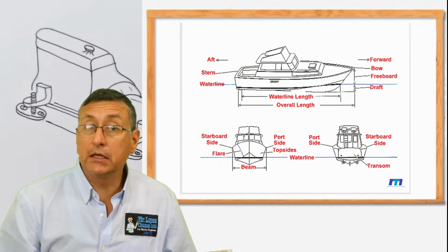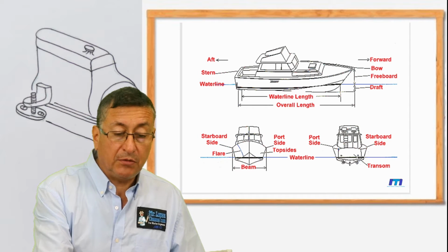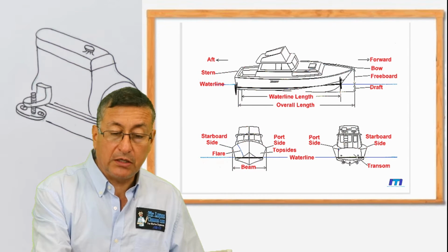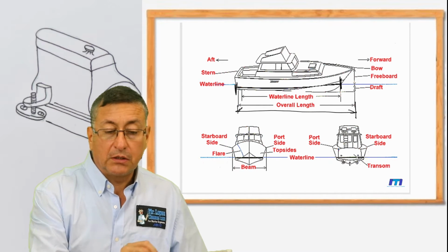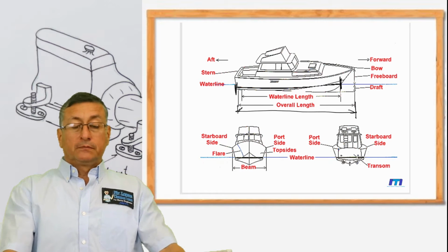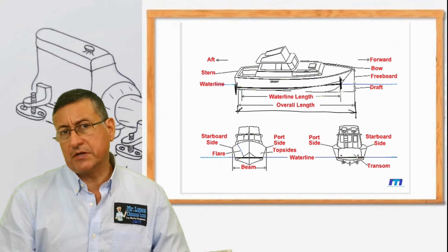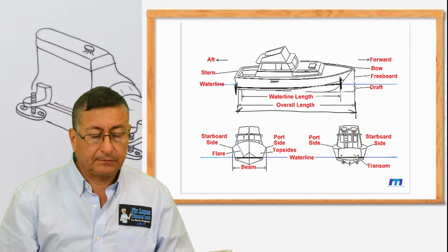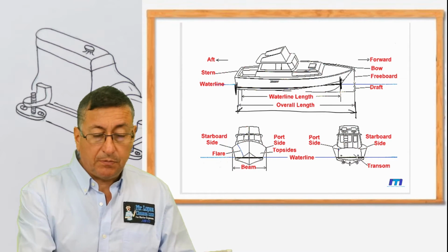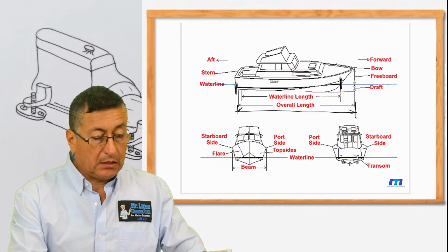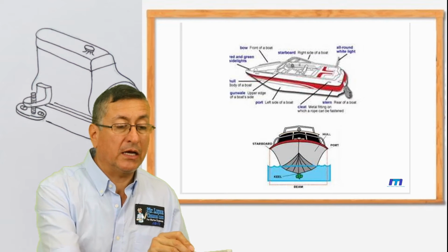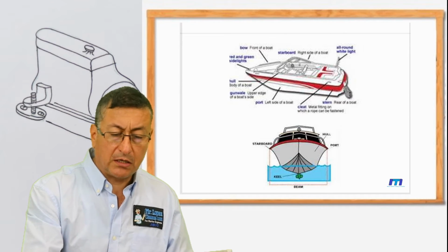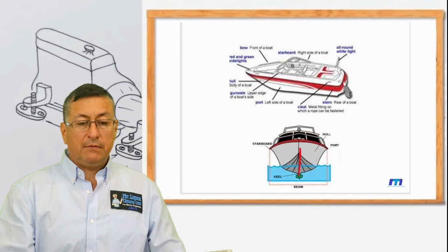Okay, and we are going to check another dimension, the water line. Remember, the water line is the distance in between the transom and this point, and this is the total length of the boat. We are going to learn right now that the water line normally is 85% of the total length, approximated. We have a port side, a starboard side. Here we have the keel. This is the center line of the boat. Here in the middle, that's the keel, right?